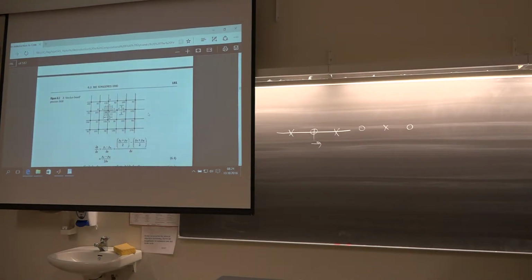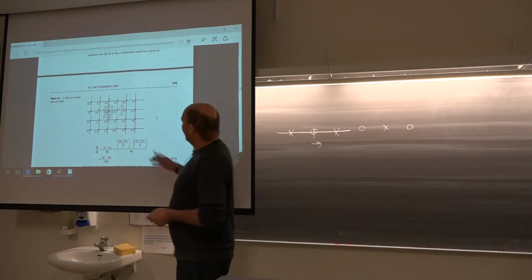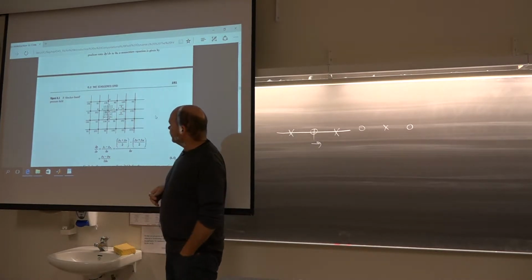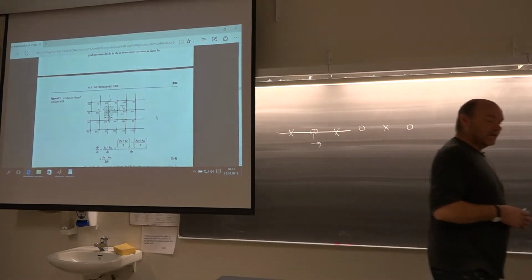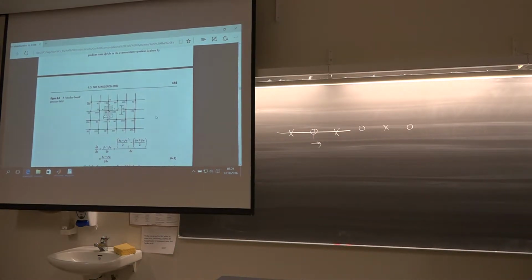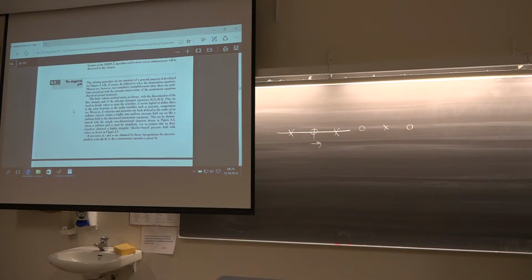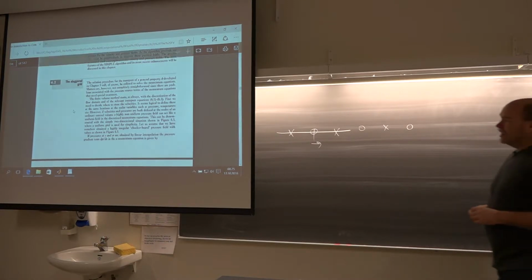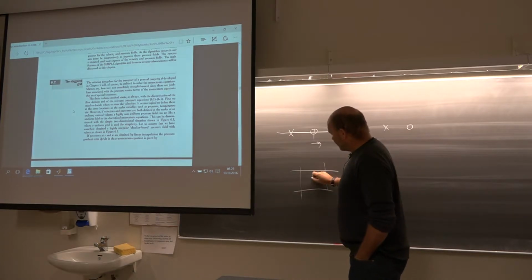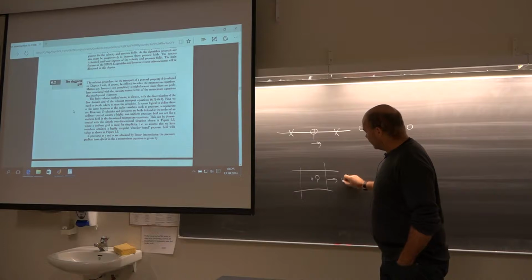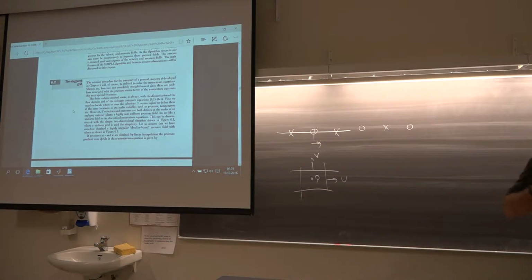And I think he has actually illustrated this here. So you see the checkerboard pattern here in 2 dimensions, 50 and 100. The 50s doesn't see the 100s and vice versa. So that is the problem. But the remedy in the 60s, 70s, that was then to use a staggered mesh, as we did with Sola. Remember, the pressure was in the center, and then the velocities were located on the cell faces. So that was one way around this problem.